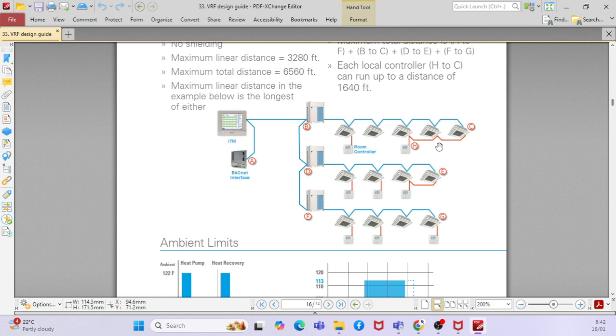Somebody used to ask me in the HAP calculation, when there is an option to select an indoor unit, chilled water unit, or say for example a DX unit, or some other unit. I say that if you go with any machine, it is the same principle. You are going to cool that particular space, right? So whatever the load, it is a heat load. So you can go with any machine which can cool that particular room, right?